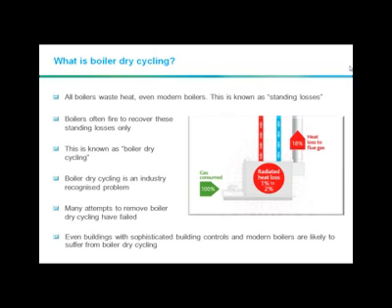Just as a very brief overview on standing losses, all boilers to some degree will have standing losses. That's through radiant heat loss, sometimes through the flue systems depending on their configuration. But this is known as the standing loss. Boilers will cool down naturally over time whether they're delivering heat or not. Another phenomenon, known commonly within the industry, is boiler dry cycling. Boiler dry cycling isn't a new phenomenon.